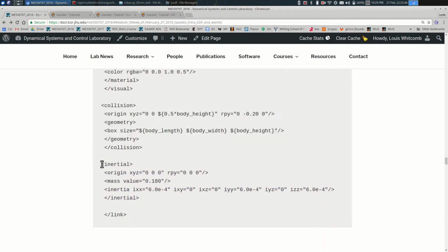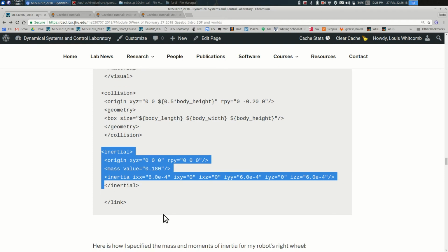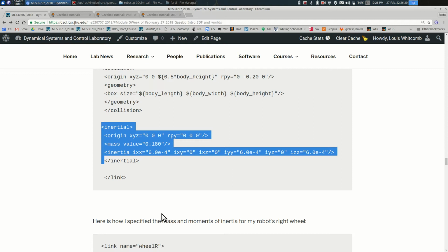And here's what's new. And there are standard formulas. If you have a uniform rectangular object of uniform density and total weight m, there are standard engineering formulas that mechanical engineers learn when they're sophomores for computing the principal mass moments of inertia. And so I used a standard formula to compute these things, and I set the off-diagonal elements of the moment of inertia tensor to 0, which is not unreasonable. If there's symmetry with respect to the center of mass, that's actually true.